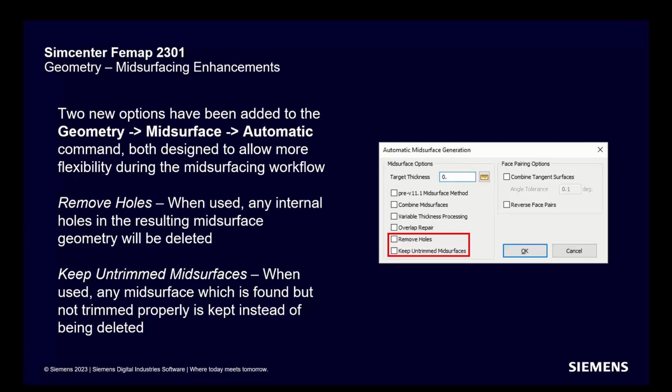if for one reason or another you wanted to close a bunch of holes and then use the original geometry later to project curves and make your own. For example, if your midsurface passed through a bunch of holes at the wrong thickness, like if there was a bunch of core ramps or something, this is something that I could potentially see this feature being useful, because then you could generate just a clean surface and then project a bunch of curves to create your own holes.